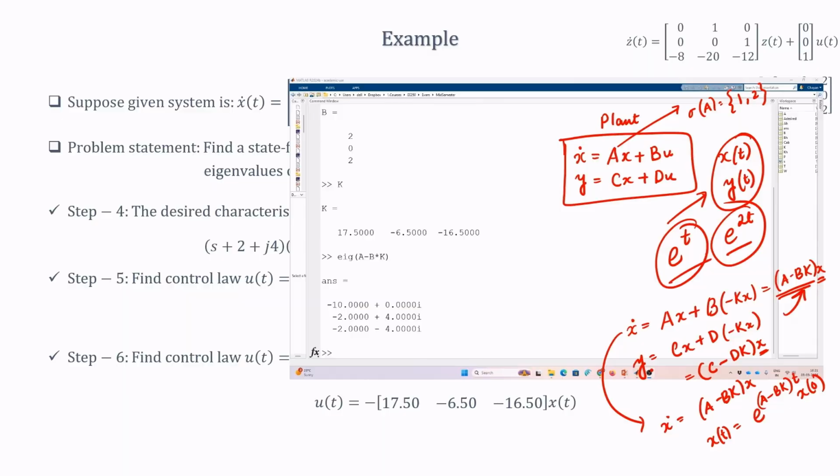Okay. And again, as I was telling, in this case the feedback is the state. In the previous PID case we were taking the output as feedback, finding the error signal and putting it into the PID controller, and from the PID controller we were getting the U that goes into the plant. Go back to the block diagram, you will remember that. In this case we are taking the states and feeding them back into the system using the control law U equal to minus Kx, and that is why this is called a state feedback controller.